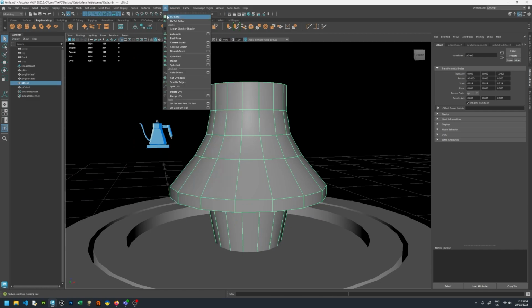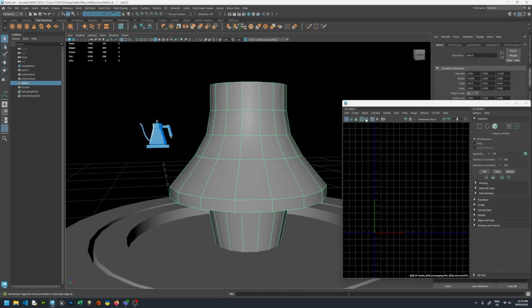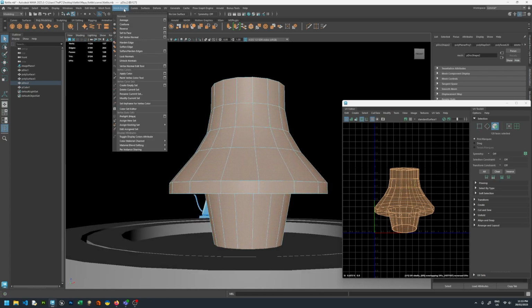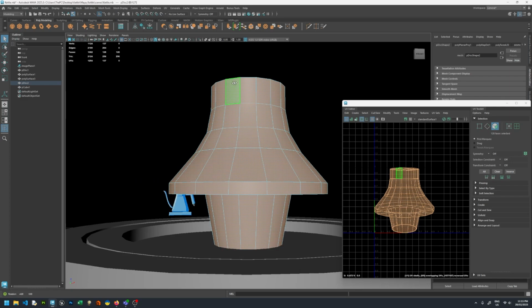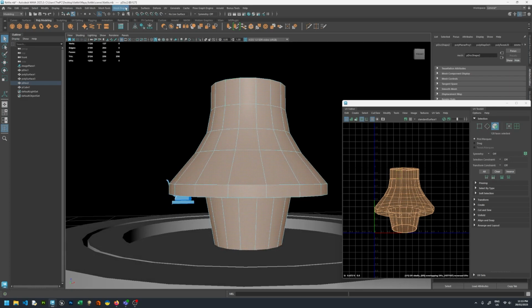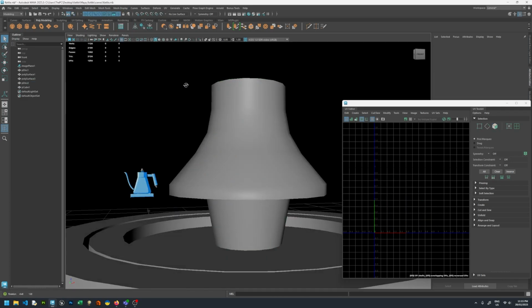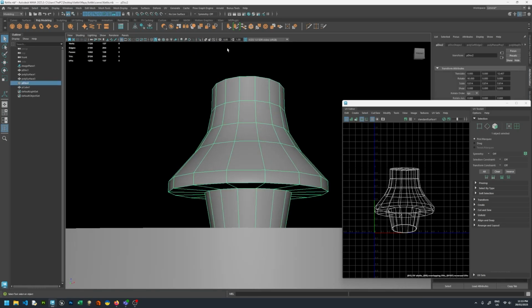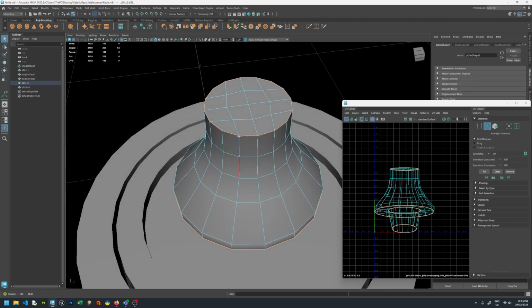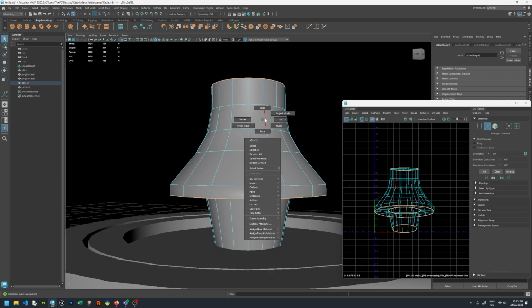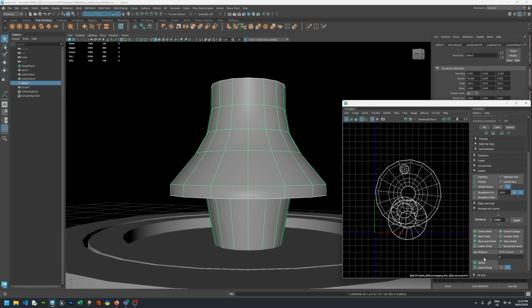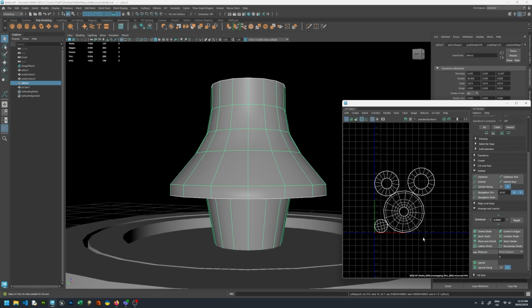Now we can start addressing UVs. I won't combine these yet. I'll do the UVs first. So delete the UVs we've got, then create a new camera base. Now we could use the auto seams to automatically cut where any hard edges are. So that's in the UV menu here, auto seams. So it's just going to cut where there's hard edges. And then we'll see how that looks when we unfold. Get out. And that looks good already, just as is.